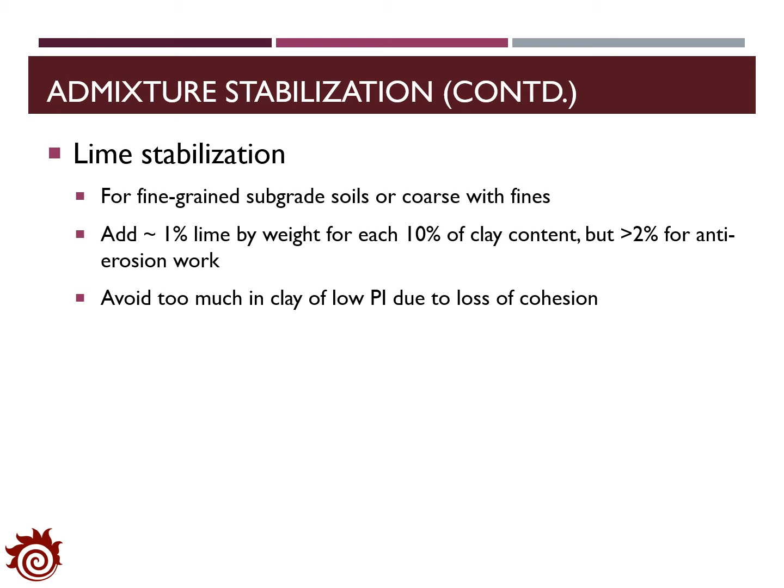However, the selection of the amount of lime should be very careful. If we are working with clay of low plasticity index, we should avoid too high a percentage of lime so that we can avoid loss of cohesion. Also, lime stabilization can increase the strength of the soil, but the strength gain is very slow with time.